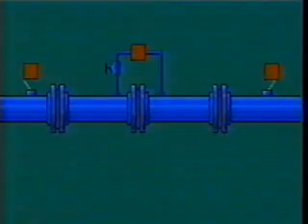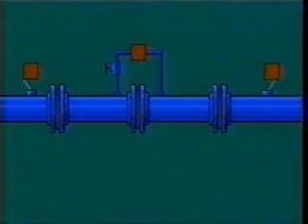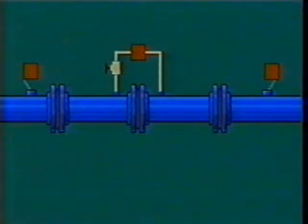Densitometers can be installed at several points on the meter run. However, the primary concern is that density is measured at flowing conditions, the same as those of the volume measurement. An insertion-type densitometer can be located either up or downstream of the metering device. However, because its insertion creates turbulence, the densitometer should be placed some distance from the meter. All piping for slipstream densitometers should be insulated to keep the temperature the same as that of the flowing stream.